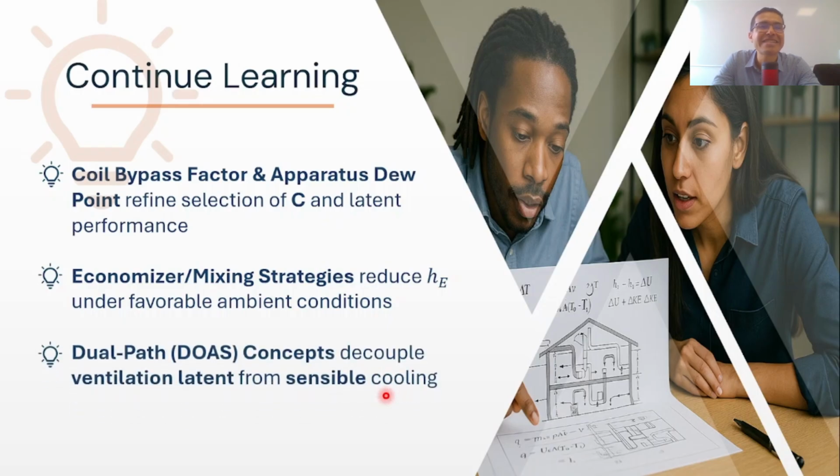And finally, investigate dual path DOA systems where ventilation is cooled and dehumidified on a separate path. This approach directly addresses latent loads and can reduce circulation airflow and fan power in many applications.